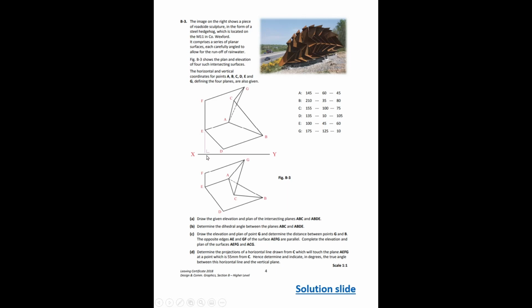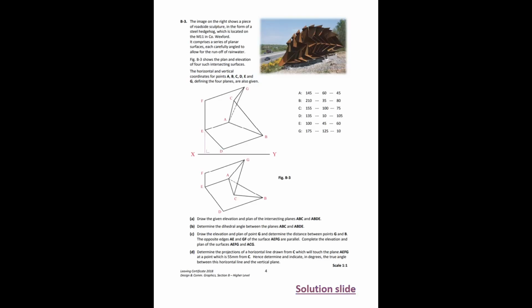Just before we start, we want to start somewhere around the center of the page. I did it slightly off to the right, but around the center of the page is a good place to start, because we know that it's going to be intersecting surfaces. This type of question always involves some sort of auxiliary view, so just to make sure that we don't lose any space on the page, it's a safe call to start somewhere around the center.